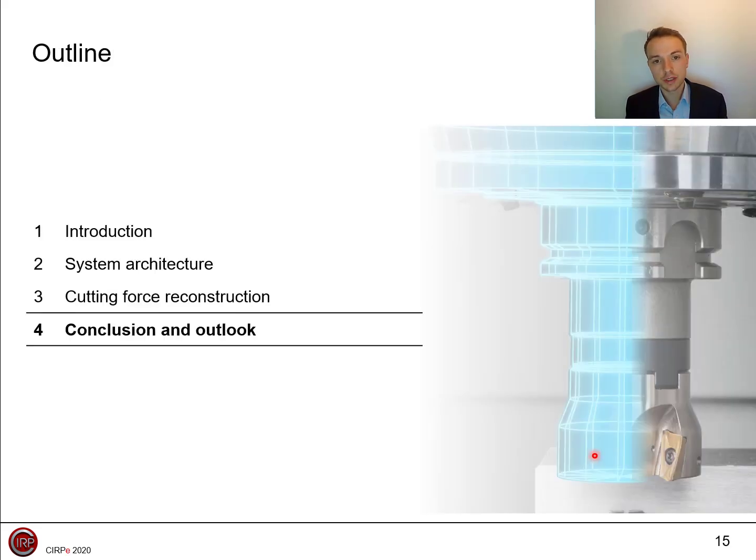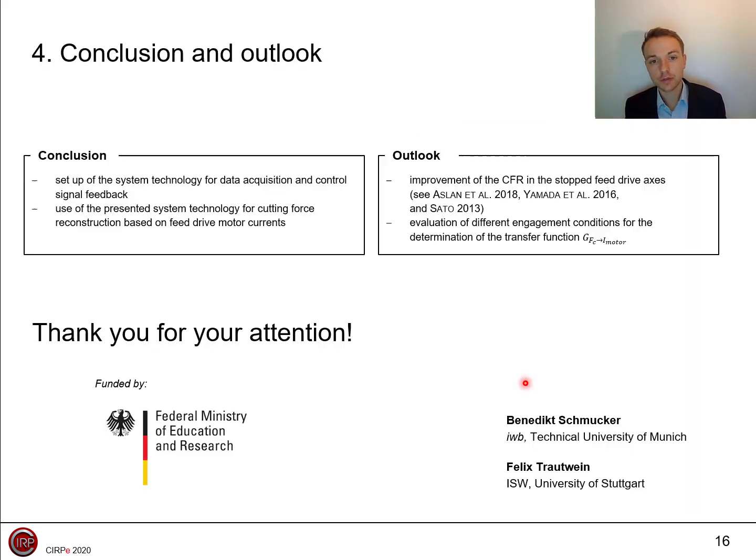I would like to proceed with the summary of the presentation and the outlook to future studies. The structure of a system technology which enables the acquisition of high-frequency machine data and external sensor data was shown. This data can be analyzed by local or network applications with the help of the ADS communication. An exemplary application which processes the acquired data is the presented cutting force reconstruction.